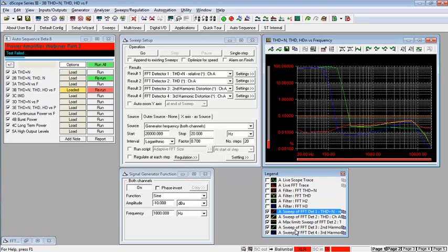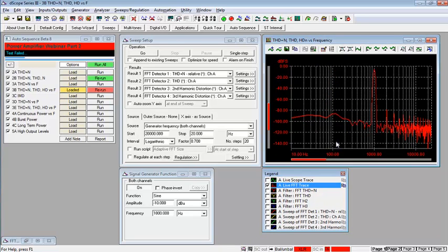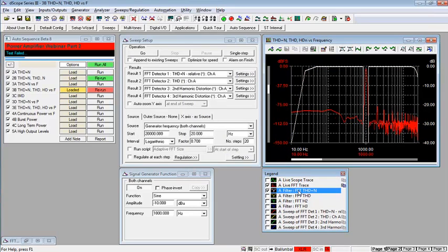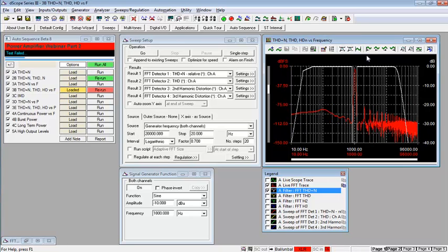So what happened there? Well, the issue here actually is that I'm using some sophisticated FFT-based analysis tools that rely on some rather interesting filters. Let me just explain. If I show you my FFT trace here, there it is. There's my signal at 1 kilohertz that you can see clearly on the screen there. I'm measuring THD plus N, I'll just change the colour of this filter actually, using this white filter. So it's just a band reject filter that takes away the 1 kilohertz tone and allows us to analyse the residual, the remainder after that filter has been applied.